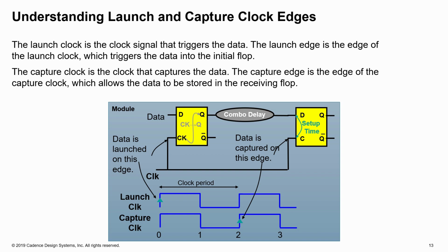And the clock that launches the data is called the launch clock, and the edge of the clock that launches that particular data is called the launch edge. And for the capture side, the capture clock is the one that captures the data, and the edge that captures that data is called the capture edge.